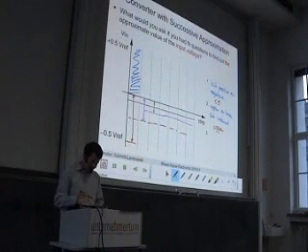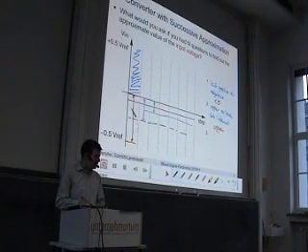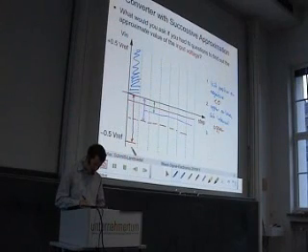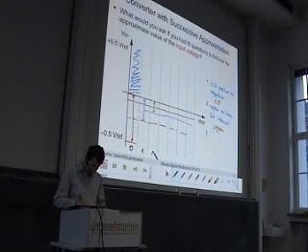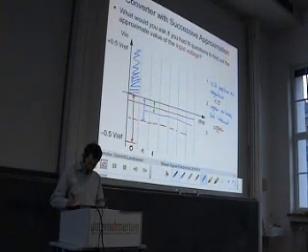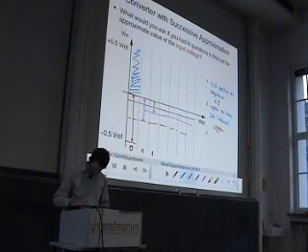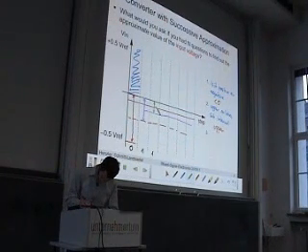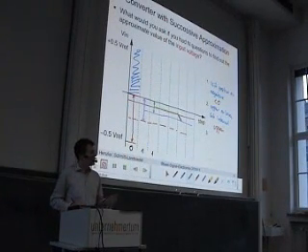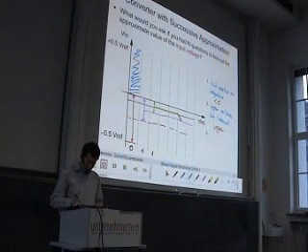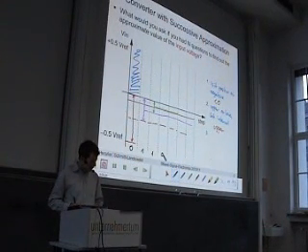So we can say, okay, the first one was that we are in the lower subinterval, so we are less than 0. So we assign this as 0. Here we say we are above this threshold, so we assign this 1. Here we are again above the threshold, so we assign this also a 1. And now it becomes a little bit difficult because of the thickness of this pen, but we can say, okay, we subdivide this interval again, maybe like this. And here we can say now the input voltage is below the new threshold, so we have here a 0.